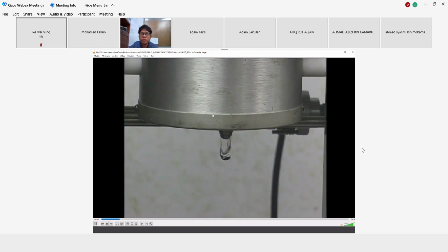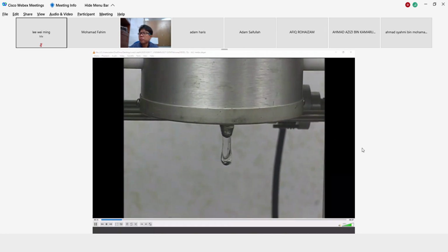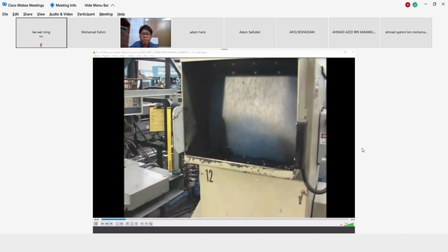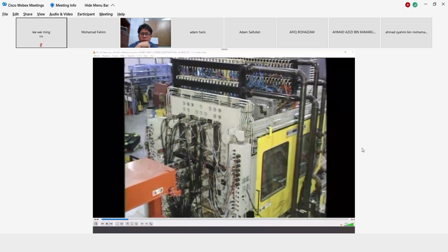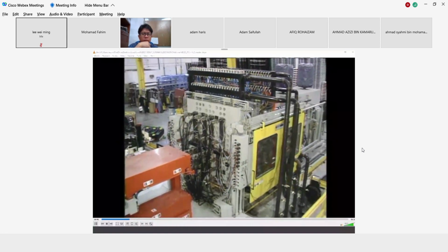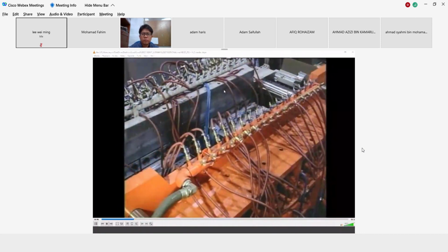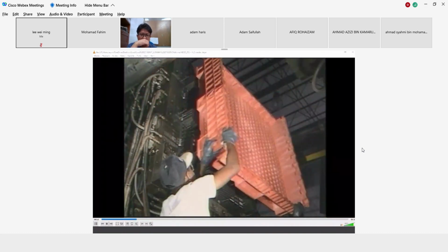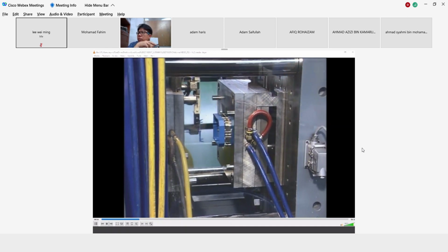Thermoplastics undergo a reversible change from solid to liquid when heated and can be cooled and reground for reuse over and over again. Thermosets undergo a chemical reaction between two reagents when heated and achieve their strength through the interlocking chemical bonds. Once molded, thermosets cannot be resoftened. While thermosets are injection moldable, most materials used in injection molding machines are thermoplastics.